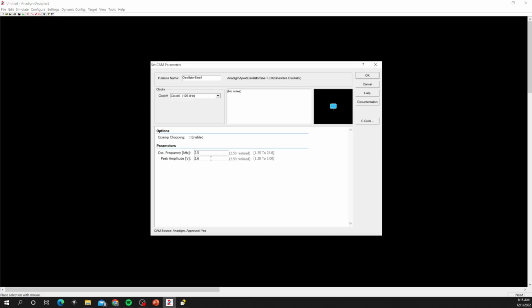As I mentioned, the FPAA actually has a limited working range, just between -3 to 3 volts. So we'll use maybe a much smaller value. Let's say we use 1 volt. And okay, it just errors out, it doesn't like us to choose this frequency range. It gives us the range. When you change the amplitude, the range will also change at the same time, you see. So let's just follow what they suggest. We'll use 5 kilohertz and click OK.